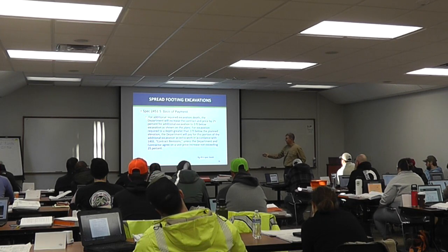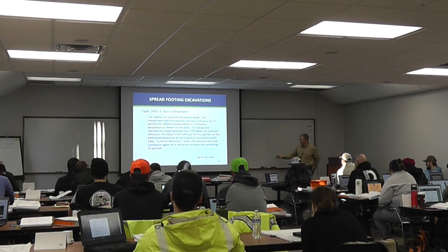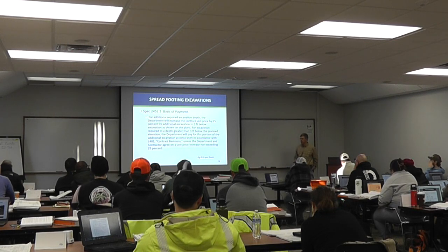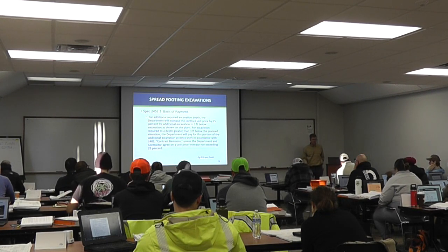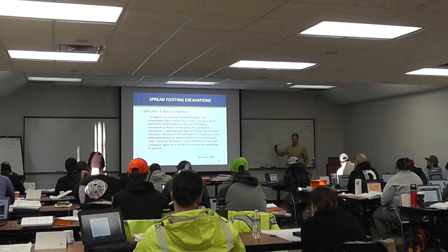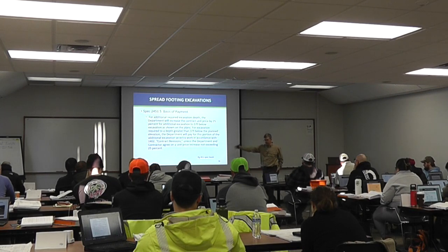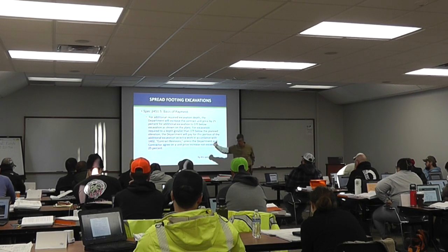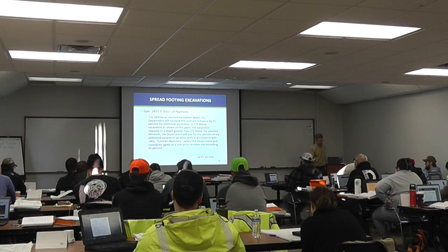So greater than that, you would need to then have extra work in accordance with 14.2, unless the department and contractor can agree. Essentially that's saying, contractor, you're not on the hook that if all of a sudden you need to excavate 10 feet down, you have to do it all for the same price that you said you're going to do for the original. We're not going to require that. So the spec book says, here's how you pay for it if it gets to 2 feet.